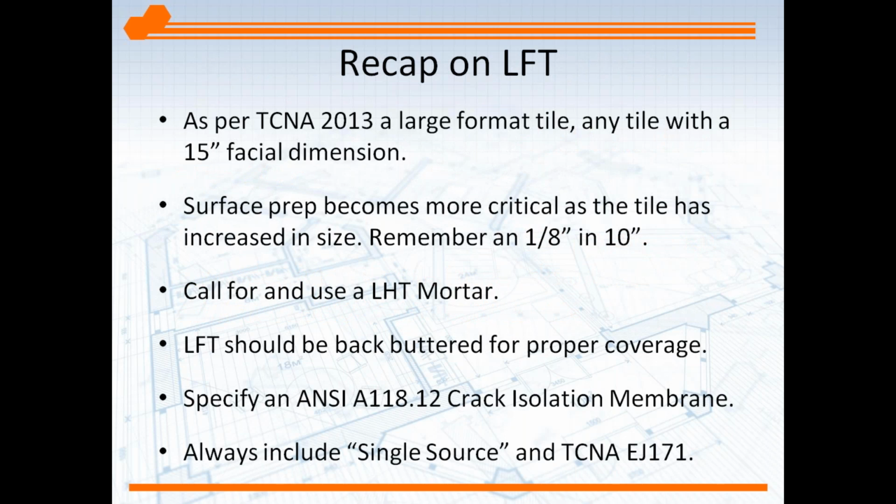Okay, so if we recap, TCNA changes. 15 inches is the cutoff there for a large format tile. Things change at that point, as we talked about. Surface prep becomes more critical. Remember, it's 1/8 in 10 for large format tile. Always use an LHT mortar. Large format tile should be back buttered so we can get that proper 95% coverage on the back of it. Specify a crack isolation membrane.